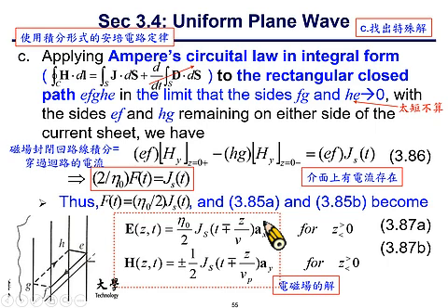And what is the result on the other side? The other side shall include the surface integral of electrical current density and the time derivative of the surface integral of displacement flux D. Because D is evenly distributed across this rectangular region, and because we reduce the width of the rectangular region to approximately 0, the second term can be neglected.